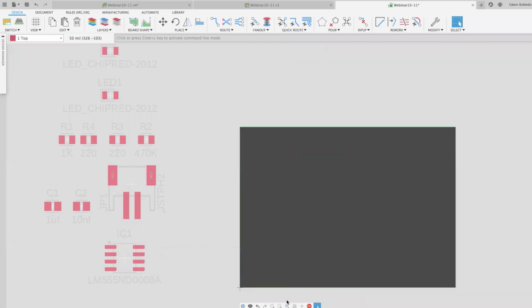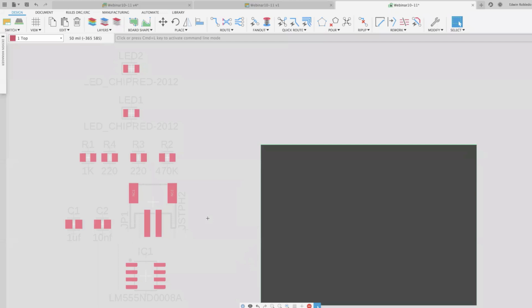The first step you should always do when you're going to start working on a circuit board is to run DRC. DRC stands for Design Rule Checker, and this is how we're going to set up our environment to make sure that our board is manufacturable. That's basically what it is. Now, Fusion 360 already has a setup of DRC, which is very conservative. Therefore, if you stick to our parameters, it's quite possible that your board will be manufactured. But let's just go over them really quick.